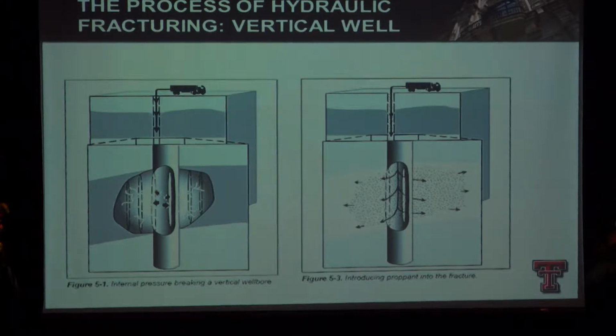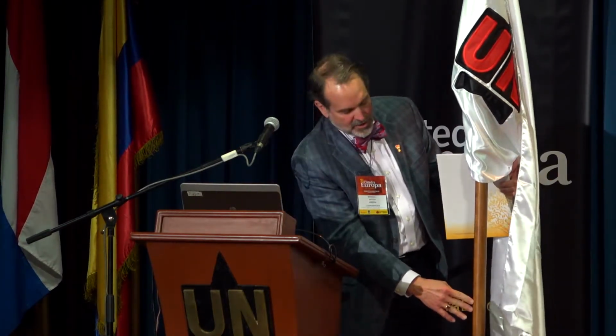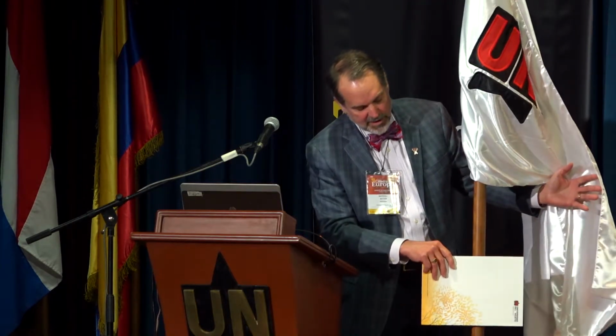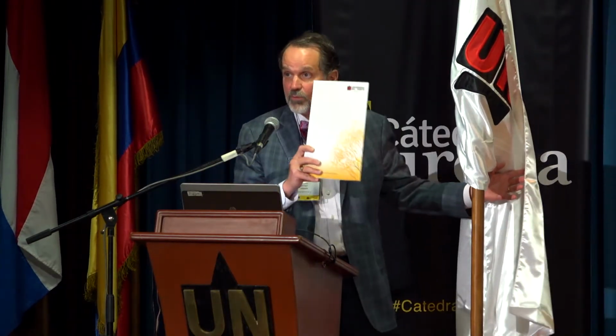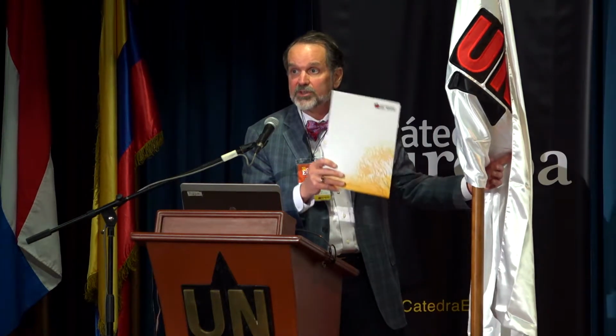So if I move your university flag just a little bit, so the flagpole represents the wellbore that you see there. As you pump through holes that we call perforations in the pipe, say here, we create a fracture that looks something like this. Okay, it actually extends both sides from the wellbore. And the fracture, this is about relative to the size of the fracture to the pipe. So the fractures are very, very small cracks made with the fluid.